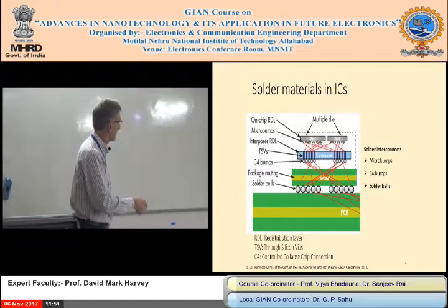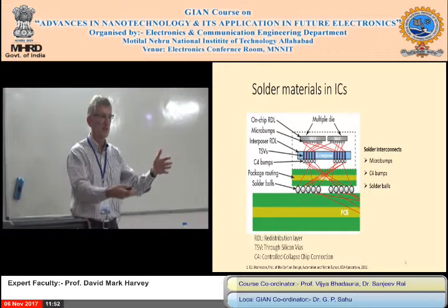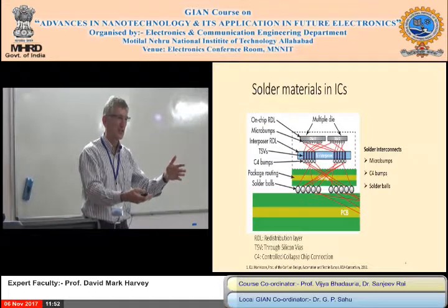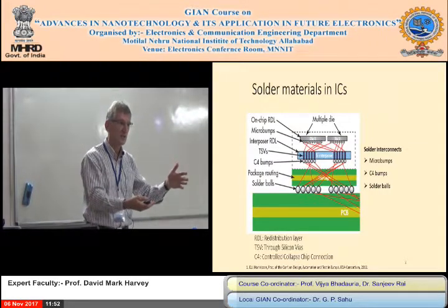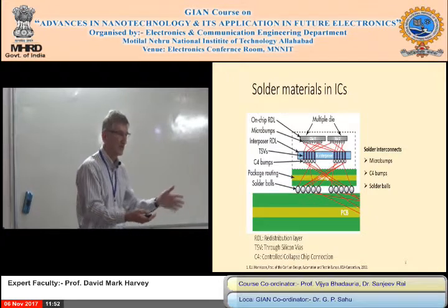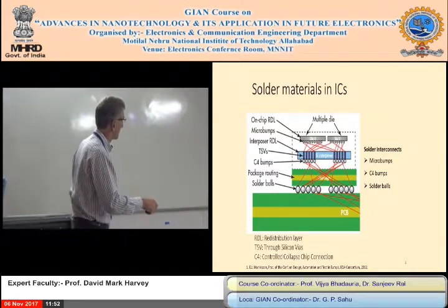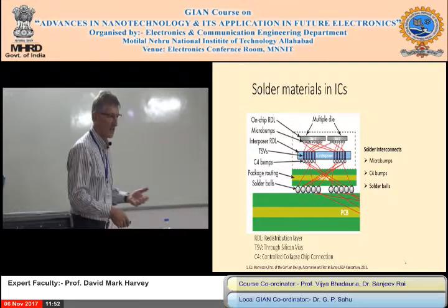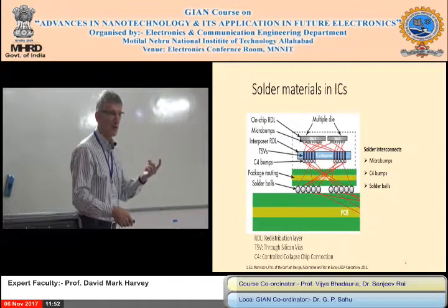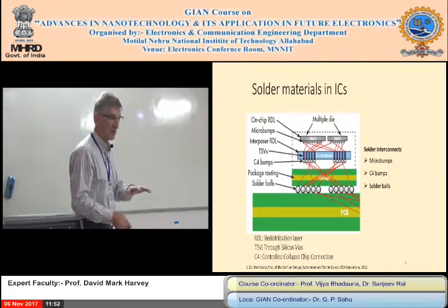But most of these solder balls are hidden. You've got a 2D solder package there underneath the package. You can't get any probe there, and you can't see them with the naked eye or the camera. So how would you test it if there's a fault? Very difficult. And that's not just the start. You've got solder balls there, and there could be hundreds, even 1,000 solder balls on a package. If one solder ball isn't made correctly, it doesn't work. So manufacturing is really difficult.